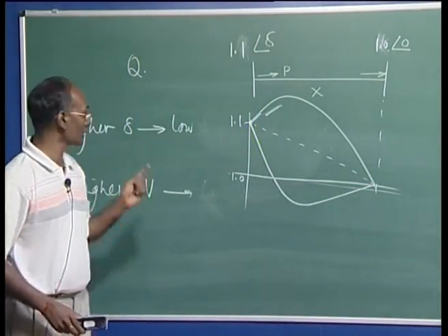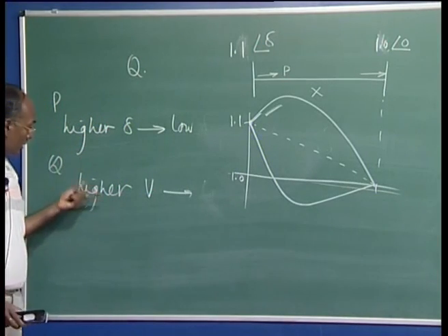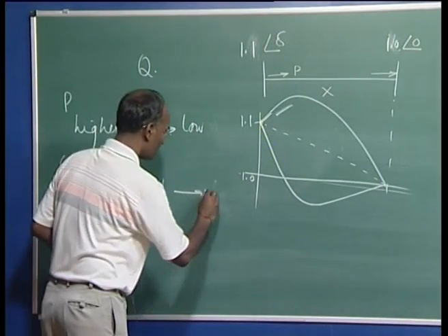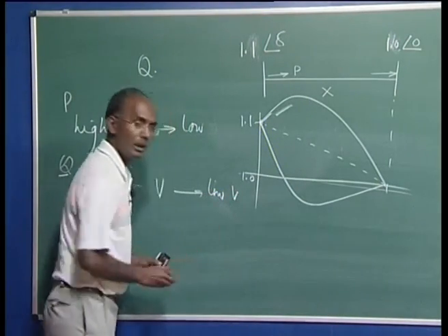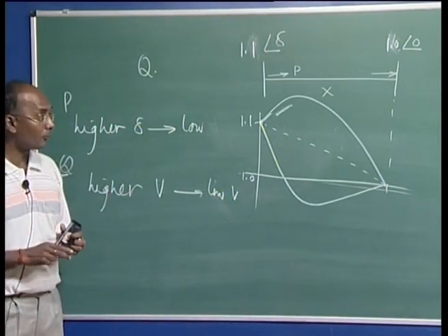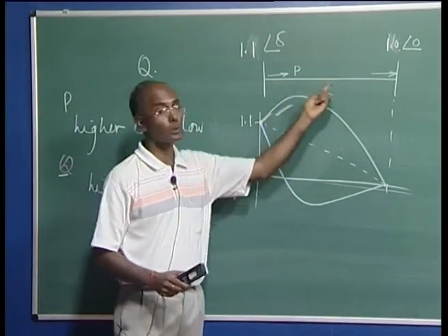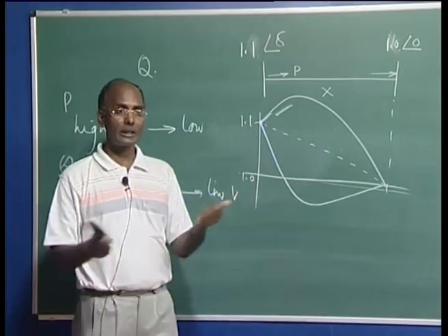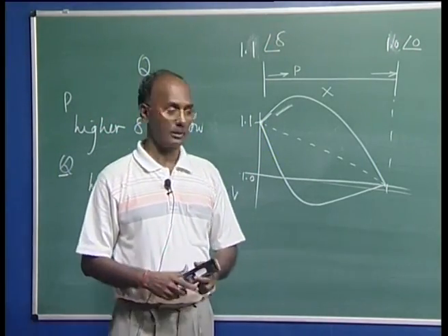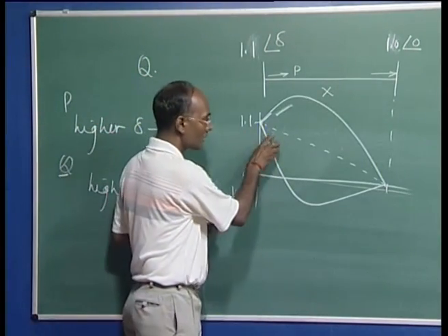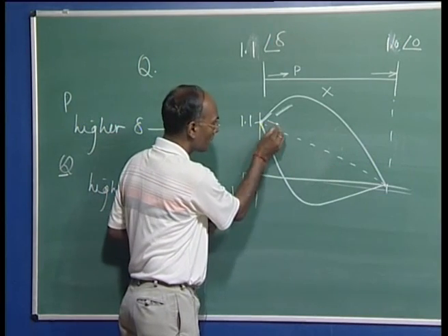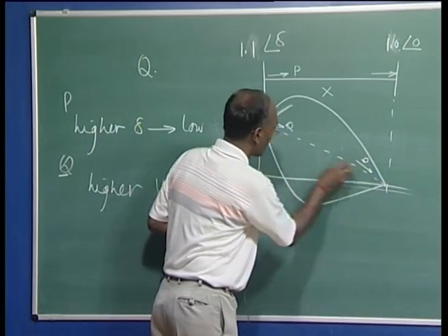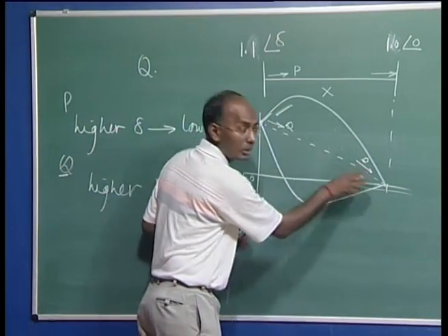So now you can see this concern here, the rule that reactive power Q always flows from higher voltage to low voltage, is still valid. But we have to see the voltage profile throughout the line as well, not only looking at the node. So that's why the reactive power can flow in either direction. For example, in this case, your reactive power here will flow like this, Q, and this will be going here, Q, because always this end is higher than this end.